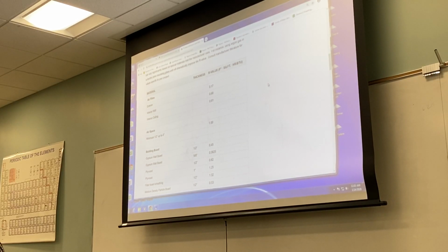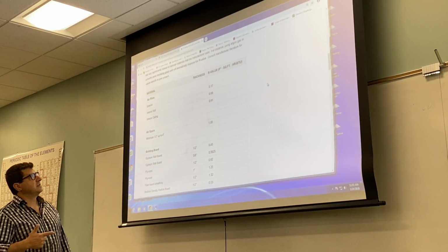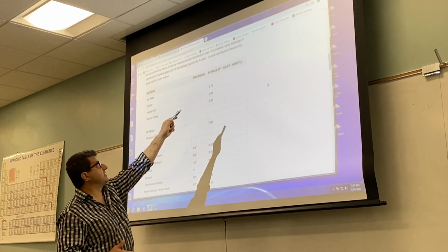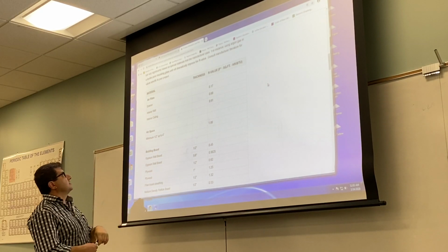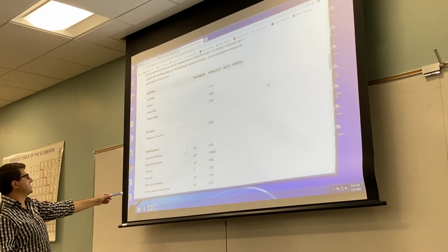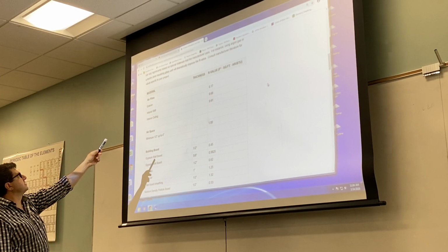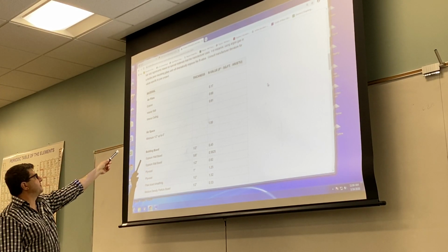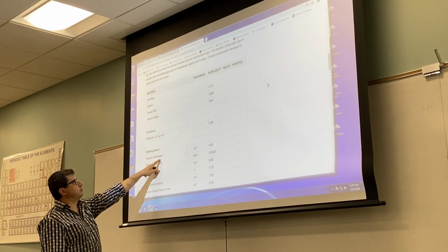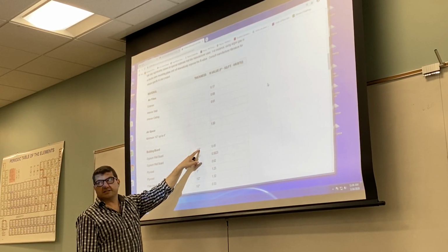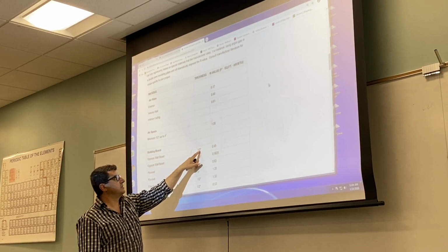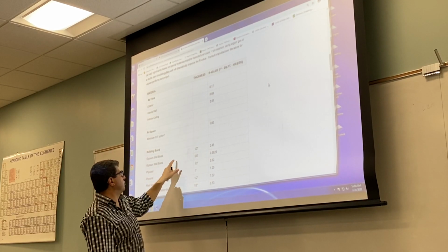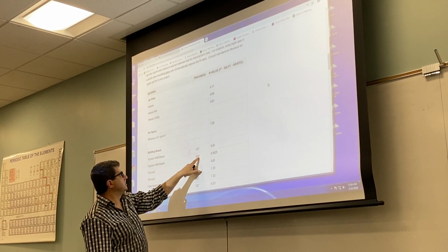A lot of websites will give you the R value in the American system, Fahrenheit square feet hour. Especially like building materials. Exterior, 0.17, interior wall, airspace, so gypsum wall board. So of course the R value depends on the thickness, you see. So it's saying a gypsum wall board 1/2 inch, 0.45. Gypsum wall board 5/8 inch, right?